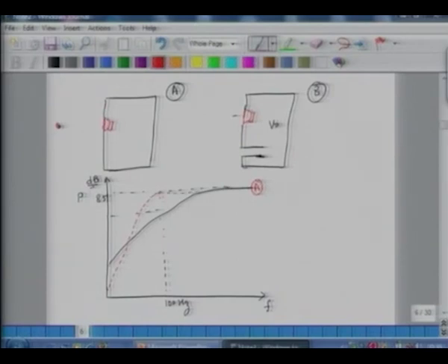So I have increased the magnitude in this frequency range. And on the negative side, you have a steeper slope on the low frequency end. So you start killing lower frequencies than a certain threshold much more steeply, but you are able to get some extra bass in this area.